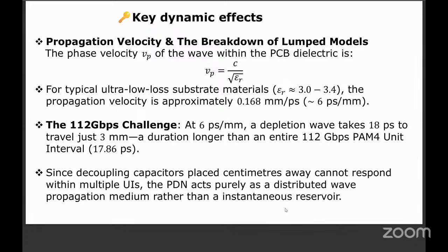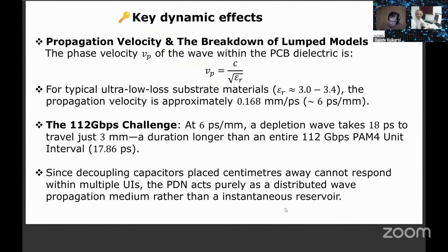In realistic terms, in mechanical design or even PCB design, 3 millimeters looks like an acre actually. If you are given a space of 3 millimeters in a BGA, it is very huge in terms of high density packaging. So that's what it takes. It is about 2.2 times. So the next set of power decoupling capacitor, the replenishing capacitor, should be available within that distance. Otherwise, it won't work. Okay.